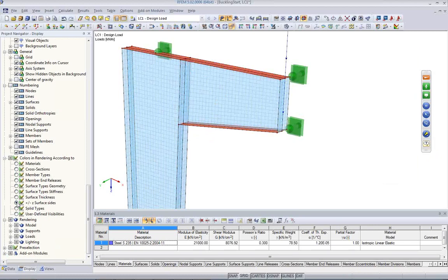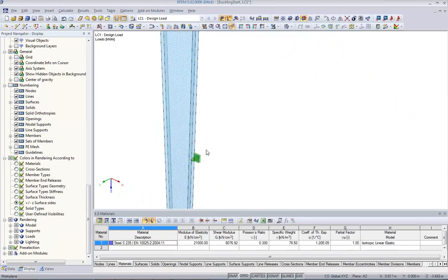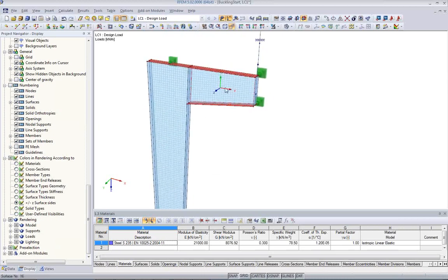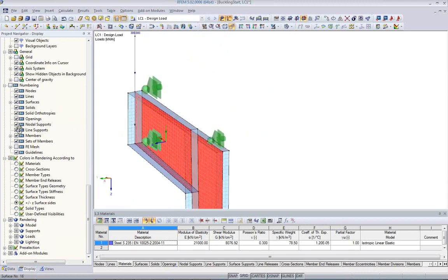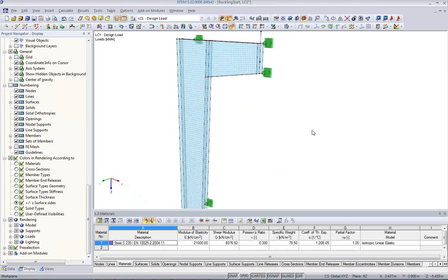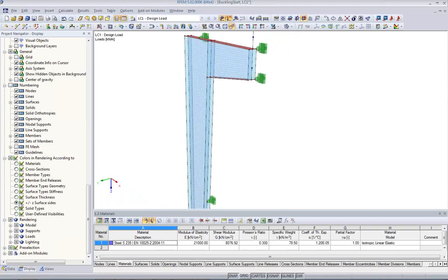Also, you can check whether the plus or the minus surface side gets different colors. It's a good thing to control structures if they have different orientation. The plus and the minus side will have different color. So you see here that, for example, the web has all the same orientation. If you look at it from the other side, it has a different color. So this is also a good way to control if everything is correct. We stay with the thickness maybe.